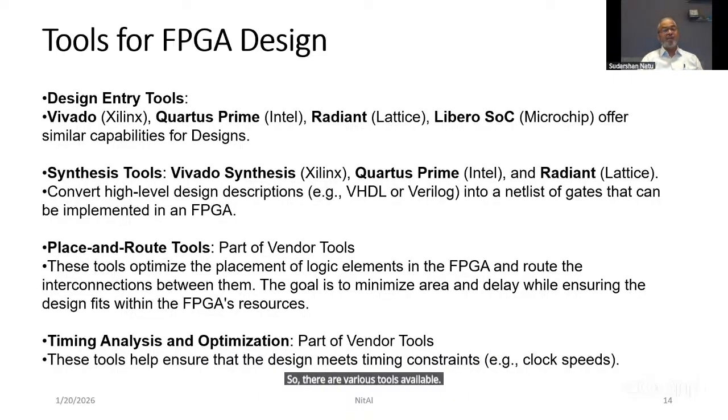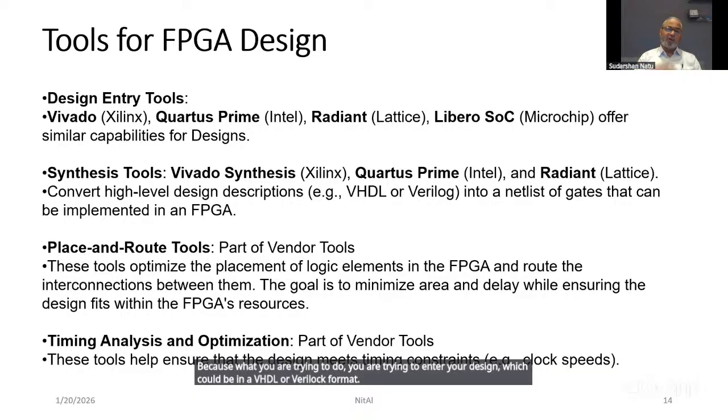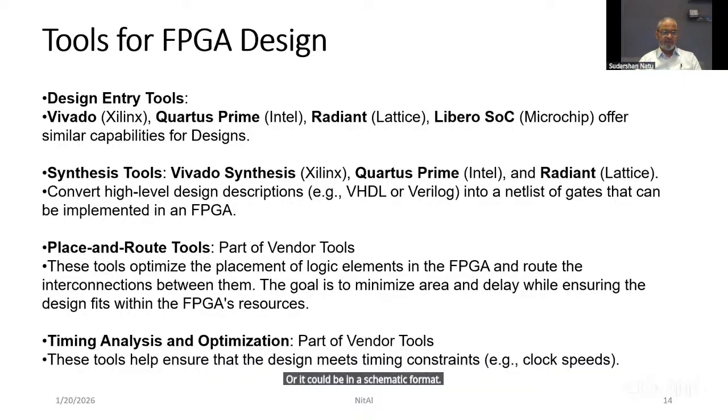Primarily what you need is a design entry tool. That's the starting point, because what you are trying to do is enter your design, which could be in a VHDL or Verilog format, or it could be in a schematic format. In any particular format, your thought process, which you have designed, needs to get entered into your tool. That's where the design entry tool comes in.